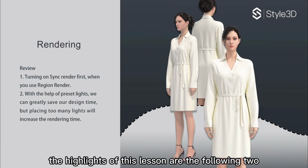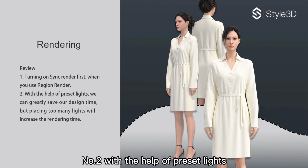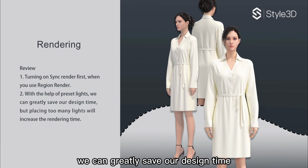The highlights of this lesson are the following two. Number 1. When you use partial rendering, you need to turn on sync render first. Number 2. With the help of preset lights, we can greatly save our design time, but placing too many lights will increase the rendering time.